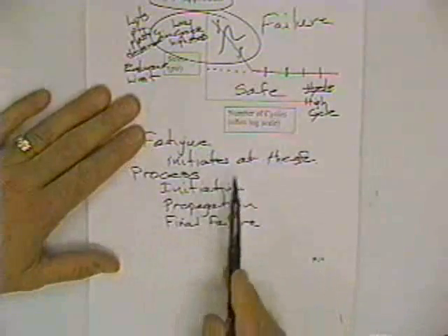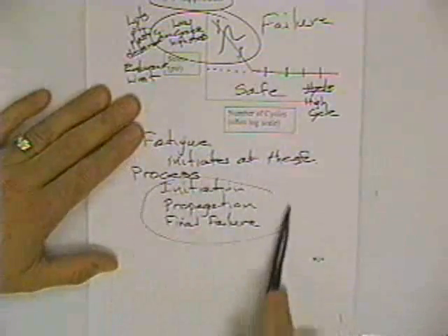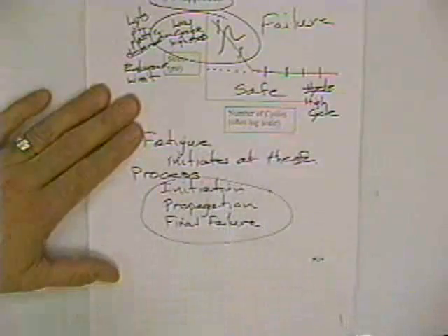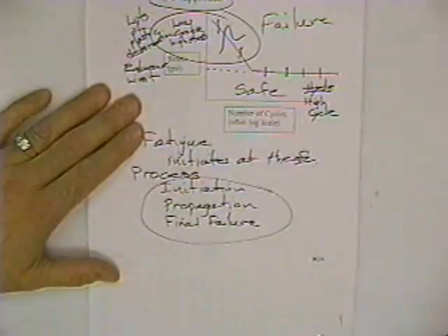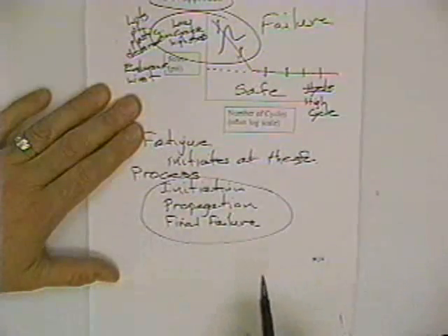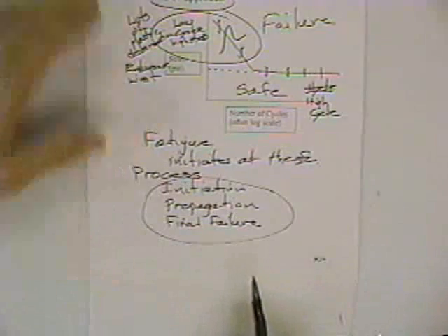And there are some techniques where you can use fracture mechanics to monitor cracks that are in materials and not have to take something out of service because there is a crack in there. There are steam generators, airplanes, railroads that move, fly, and generate electricity with cracks in, but they are safe to use.